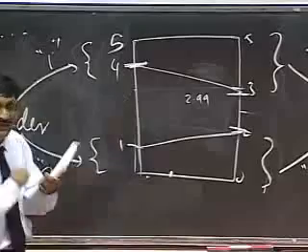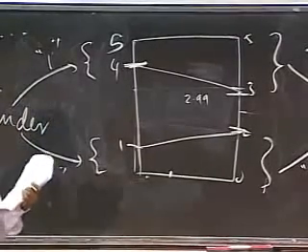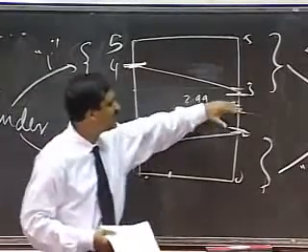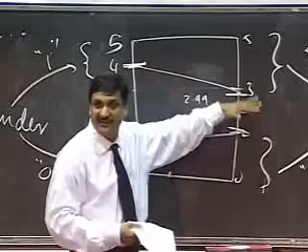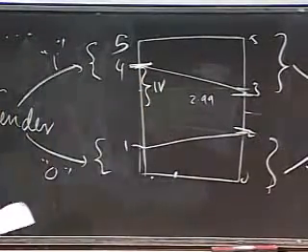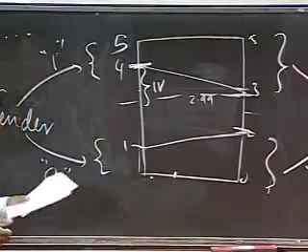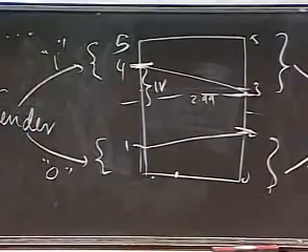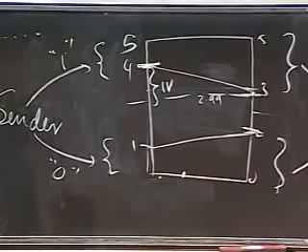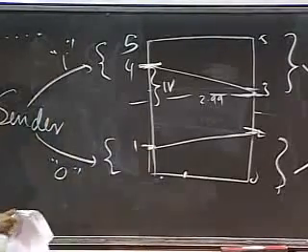So if I sent a 4 and sent this over a long cable to you, the value can be beaten up by noise to such an extent that you may begin receiving 3s, but nothing lower than a 3. So this is a noise margin, 1 volt. Similarly, for a 0, the noise margin is also 1 volt. So let me label these. There are 4 important thresholds here. This threshold is called